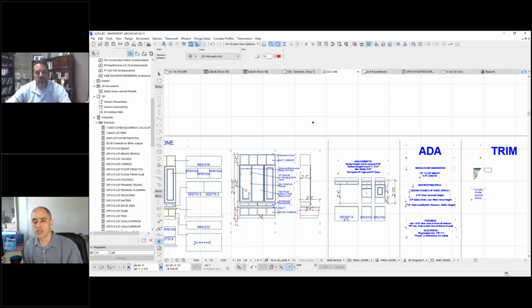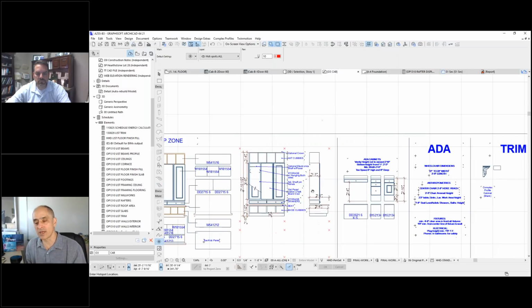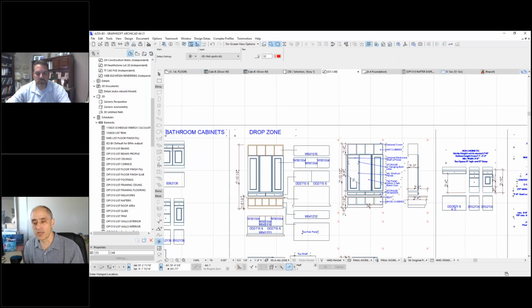What you're using it for here is, when you place this view in a layout sheet, you want to crop it to the boundaries of where those X's are, so it fits neatly into a grid on your layout sheet. It's purely for convenience in this case, but you can also have hotspots that help you align things, in 3D elements too.